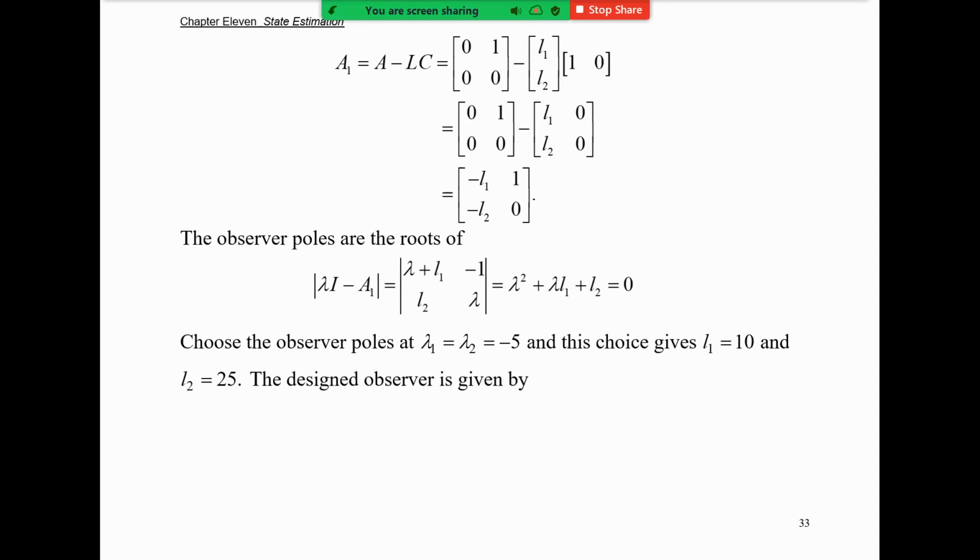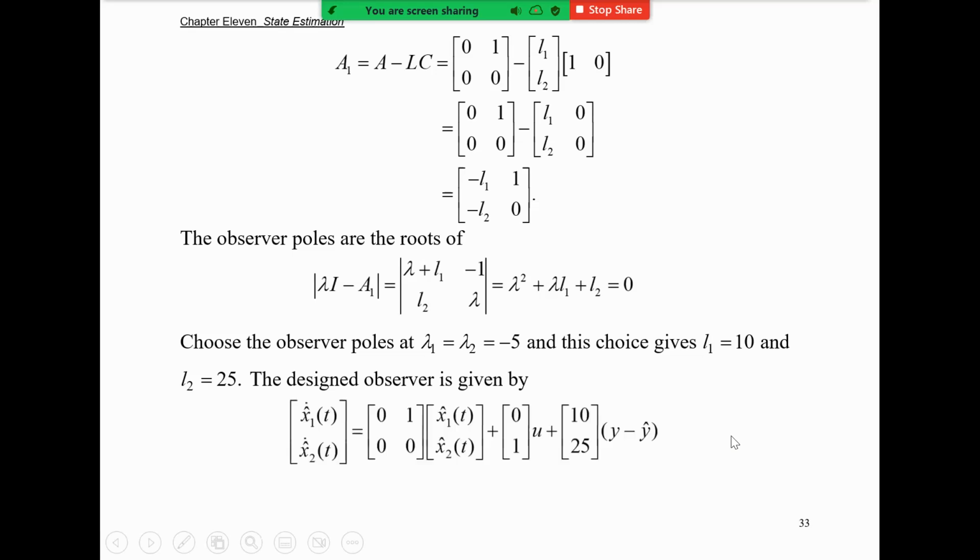After this whole course, if you give me some unstable system, it means you missed some of the critical part of control system theory. Everything has to be stable. So therefore you get the desired characteristic polynomial, you put it in, then you get your design of L1 and L2. Finally, you say, okay, this is the observer.